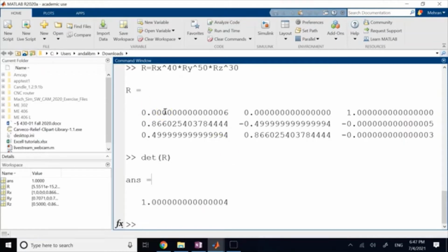And you might say, well, where would you get all of these errors? Well, I'll tell you, when you do lots of rotations after each other, right? So you want to calculate the current orientation of the coordinate frame, and you go over lots of small rotations from the initial to the final, right? So let's say your system has a controller. You want to go from orientation 1 to orientation 2. And each time you have incremented the rotation, through a loop, through a numerical solution, changing your angles bit by bit to ultimately get to your final orientation.